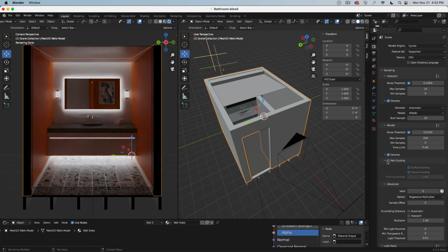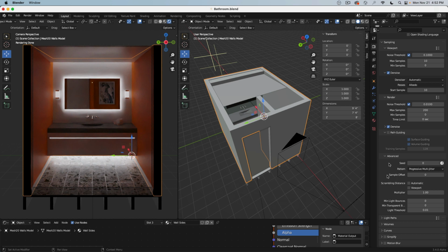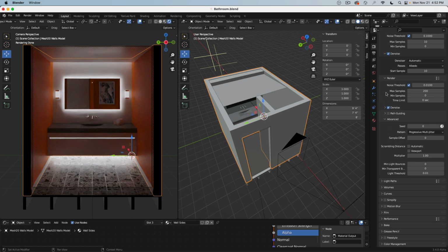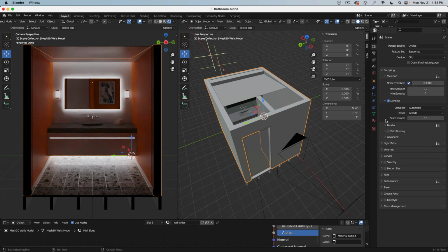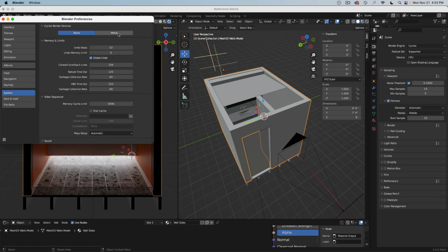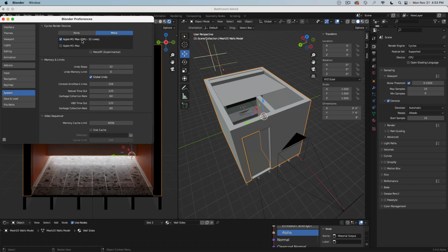And we have, do we have any other interesting elements here to note? No, this is pretty much, we can ignore for the moment. So it's basically the viewport and the denoising. Based on the system, we can render CPU or GPU. GPU is faster when, let me go back to here for one more time. So I'm here on a Mac. So I will set this to the GPU to render. And if you're on a PC with an NVIDIA card, you might have CUDA here. So you could use this.